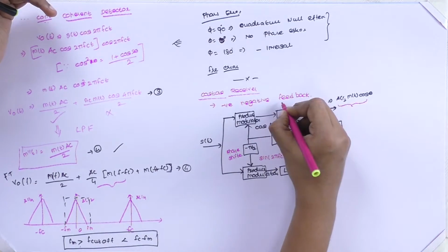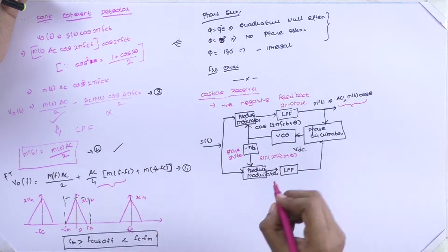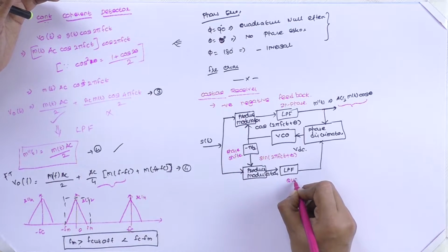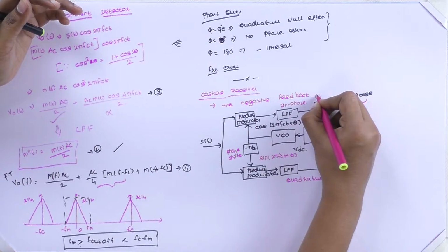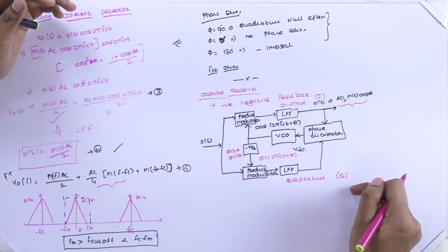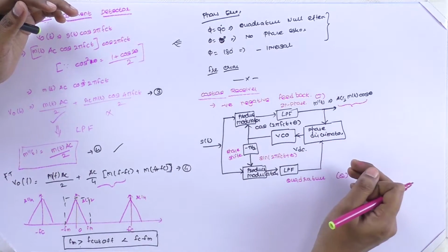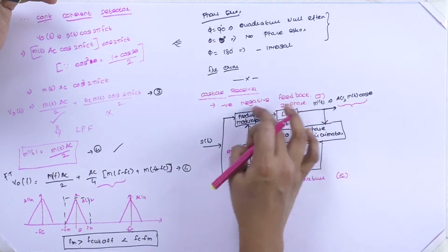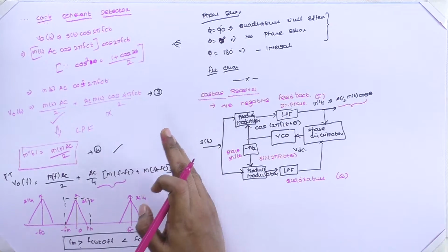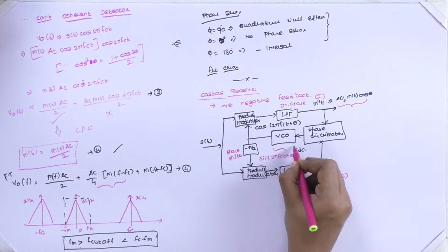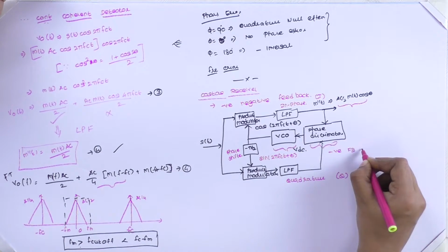It consists of the upper channel, which we are going to refer to as the in-phase coherent detector, and the lower channel, which we are going to refer to as the quadrature coherent detector. In short, we refer to them as the I channel and the Q channel. The I channel and Q channel are interconnected in such a way as to achieve a negative feedback system. This negative feedback system has the objective of maintaining the local oscillator carrier in phase with respect to the carrier oscillator used on the transmitter side.